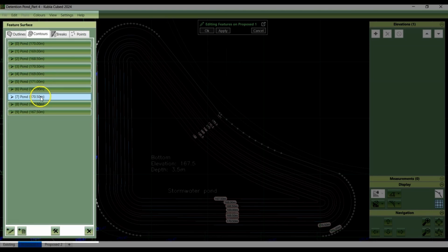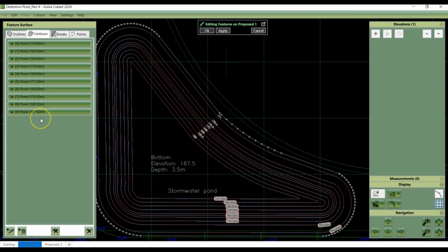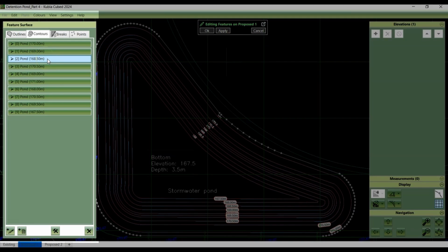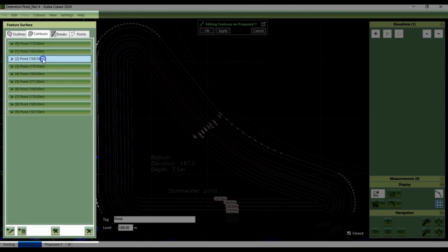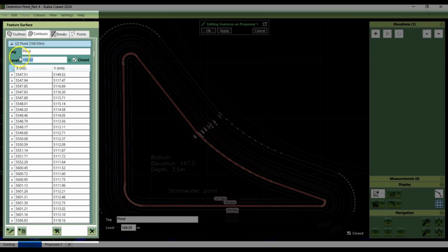It's important to check the contour lines as some files import lines and points at a default value of 0 because the Z elevations in the CAD file are not always set to their true Z value. While this project does have the Z elevation set, it's good practice to check and then you can adjust if necessary. We can reset the levels by double clicking on a contour line and entering the correct value.